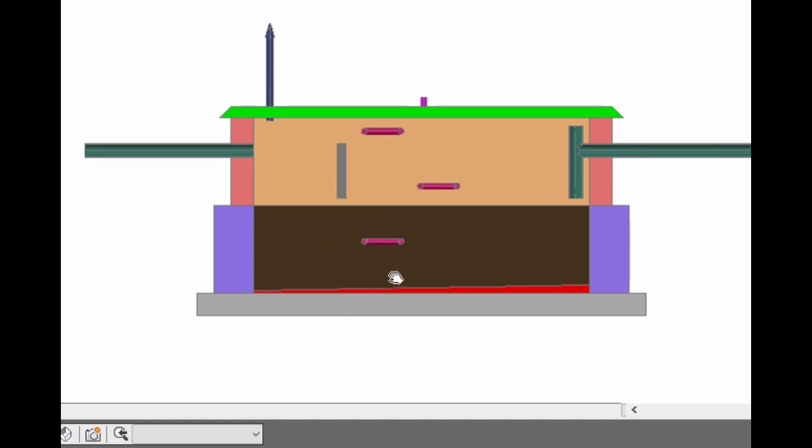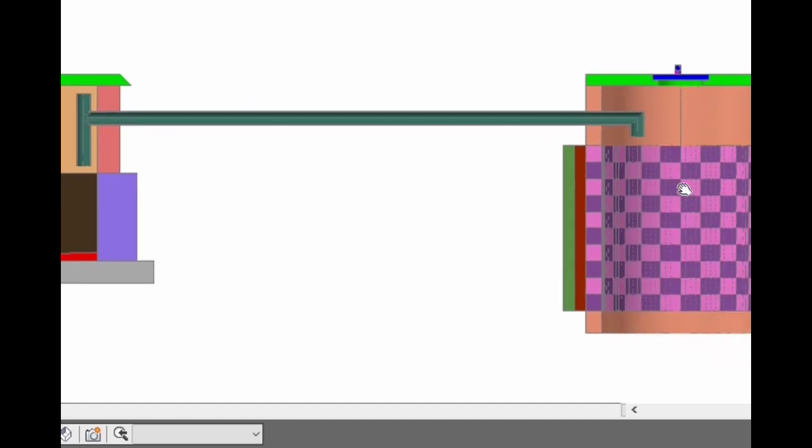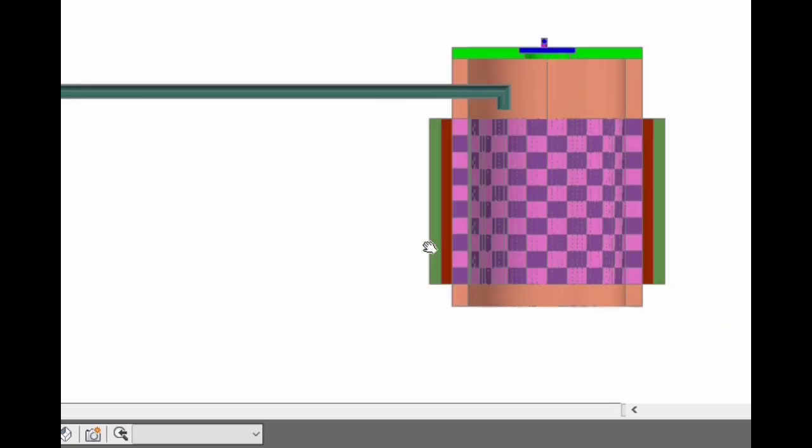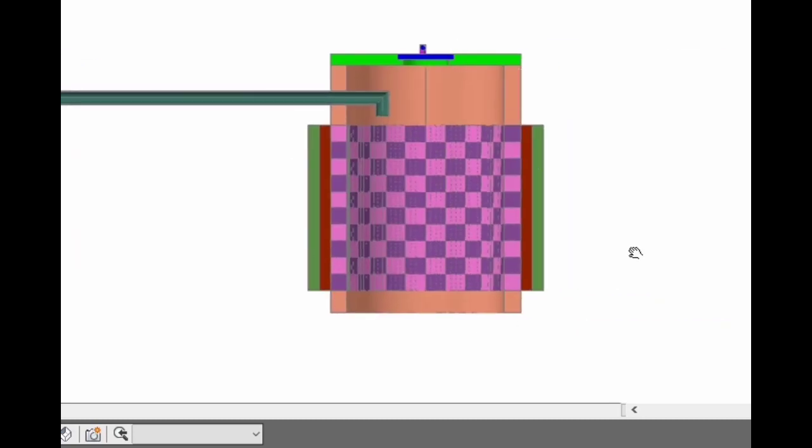The sludge will be collected here and in due course of time it will be removed through this opening, and this is the T joint that has been provided to take out the effluent that has been collected here. We are not going to take it, it is an automatic process that takes place and flows in the pipe and falls into the soak pit. And the soak pit, as you observe here in the cross section, you can see the second class brickwork that has been provided at the bottom as well as at the top.